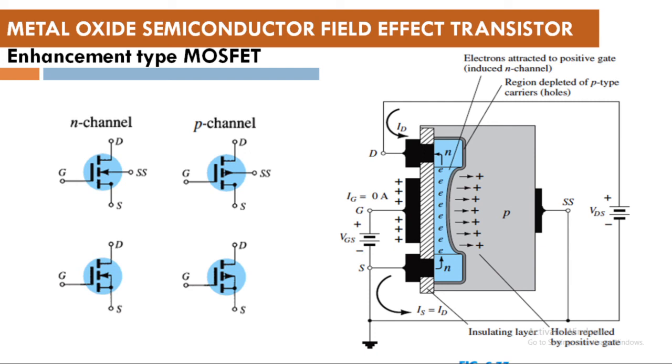But when you are making any circuit which has switching characteristics, like digital circuits, there you will need an enhancement type MOSFET which can easily switch between a particular potential and zero. You may require certain current or you may not, so there will be availability of channel or there will not be availability of channel to cut off the transistor.